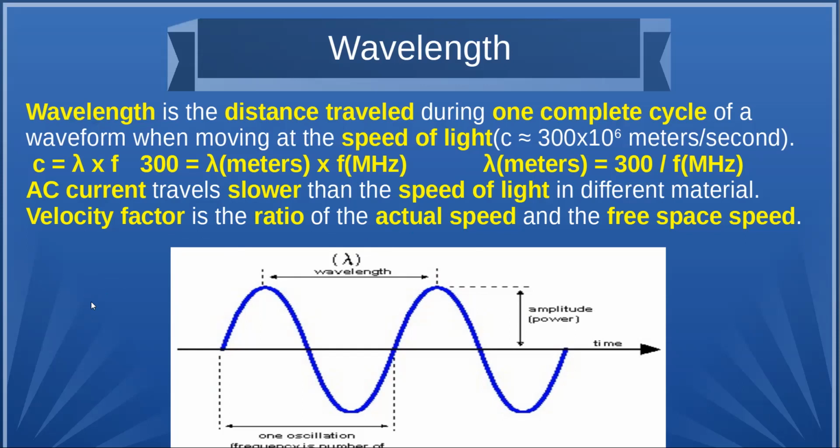But it'd be close enough that you can guess the right answer. If you use the correction factor, you get the same answer as on the exam. And they're using 0.95 for the correction factor for normal copper wire. So is the correction factor given on the exam, or do we need to know it? In that particular question, yes.